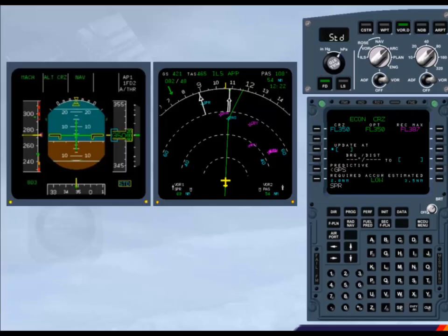The second method is to insert a VOR DME ident in the bearing distance 2 field on the PROG page, and to compare the computed bearing distance with the raw data on the ND. We have typed the VOR DME ident, SPR, in the scratchpad for you.